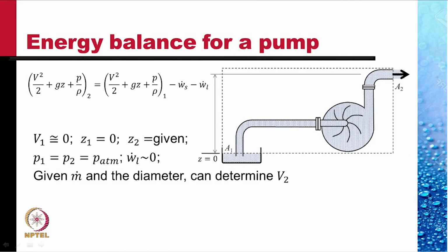So, the applicable equation is the engineering Bernoulli equation or the extended energy equation. Here, we know at 1, the inlet, the surface of the tank from where the water is coming from. If the cross-sectional area A1 is very large compared to the area A2, then the velocity at 1 is negligible.